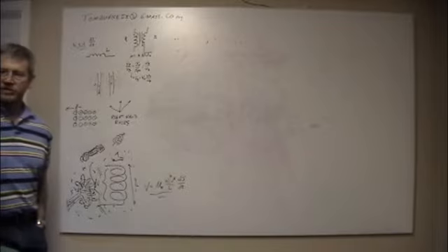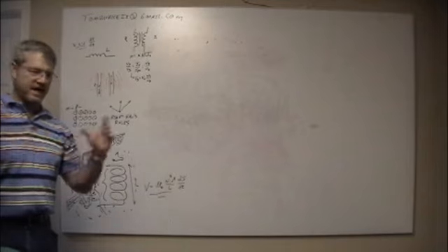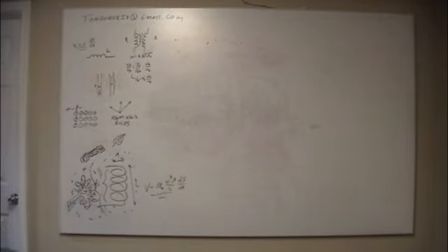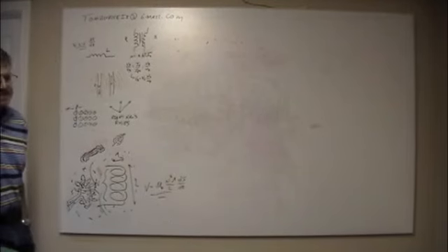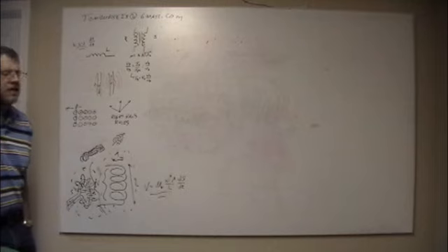I've worked with triple shielded stuff where you have a shield and then a twisted shielded pair or something like that. Your standard high-end coax these days is quad shielded because they're trying to push so much bandwidth through it. Your cable TV stuff that you use in your house is quad shielded.